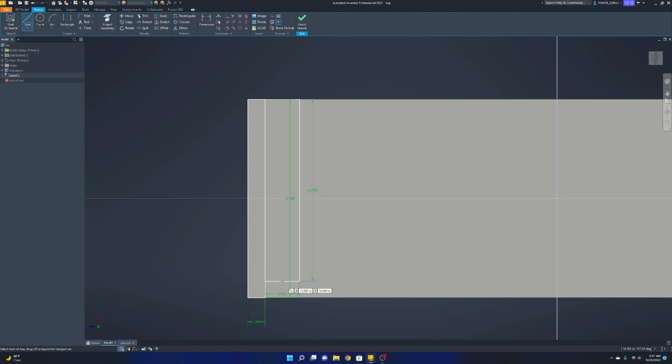So I'm just going to draw a line through here, just so I can understand the center of this. I might redraw that and feel confident in that. There's a little green dot that pops up when you're right there. Yeah, so 11, cool. And then I'm going to kind of run across this line. Okay, and there's the midpoint. Right, and so if I go right here, I can grab the midpoint, which is right there. I'm going to create a circle along here.